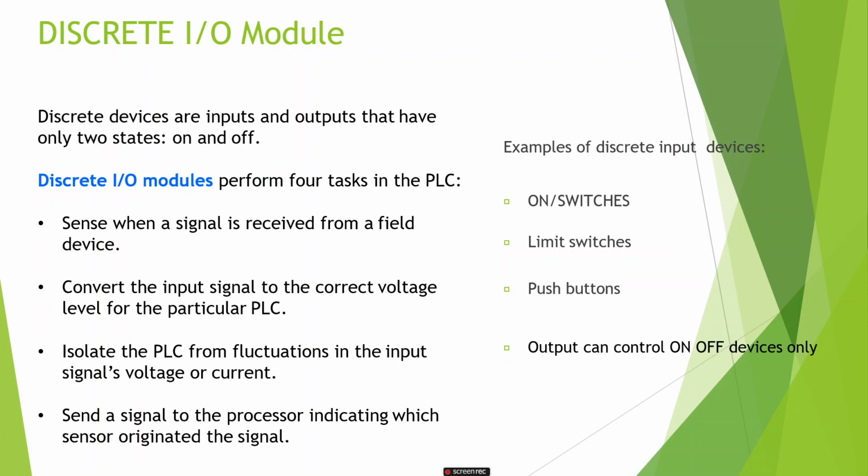The most common type of I/O interface module is the discrete type. This type of interface connects field input devices of an on-off nature, such as selector switches, push buttons, and limit switches. Likewise, output control is limited to devices such as lights, small motors, solenoids, and motor starters that require simple on-off switching. The classification of discrete I/O covers bit-oriented inputs and outputs.